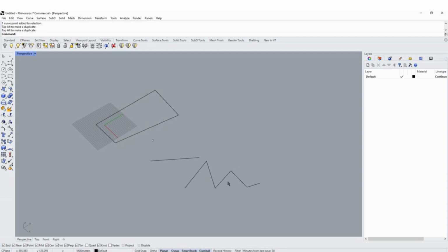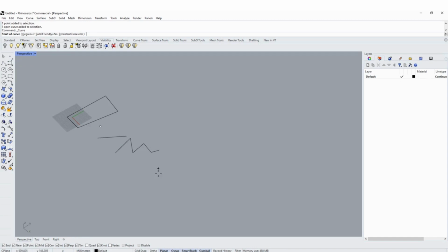Let's go and test some more options. So we have the rectangle, we started, of course we ruined it already. The point, the line, the polyline. Let's do a free line. It's a free-formed curve. With the free curve, you're not drawing the line, but you're defining the points that control this curved line.